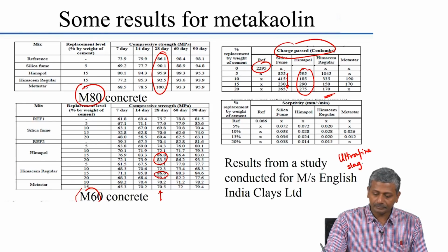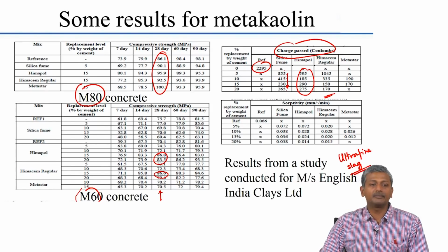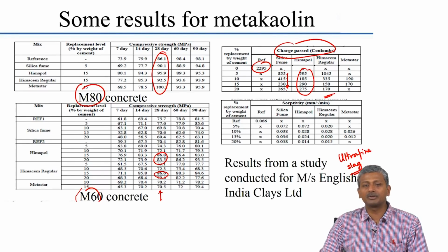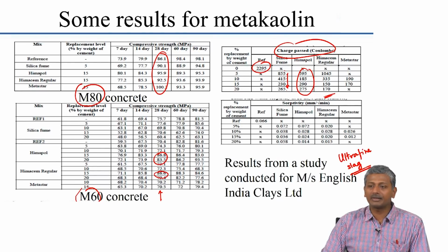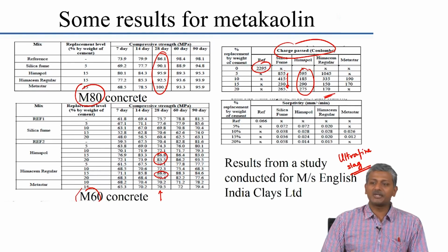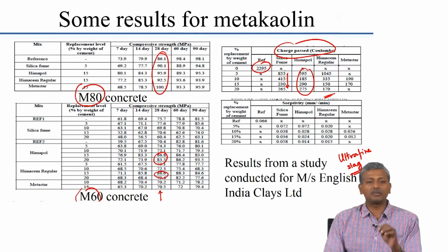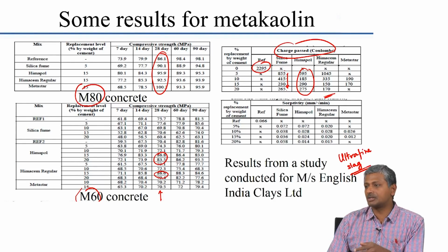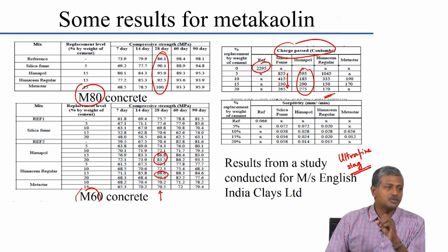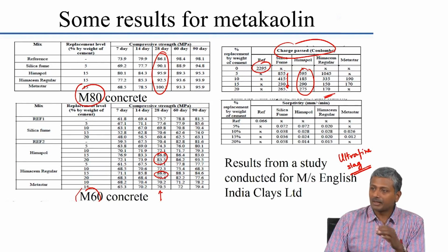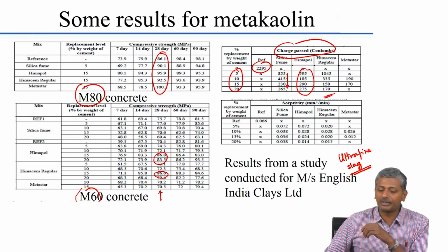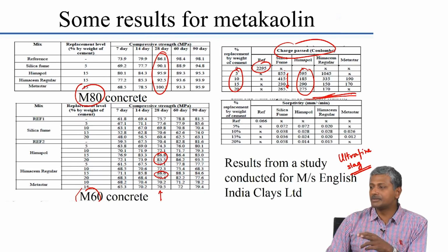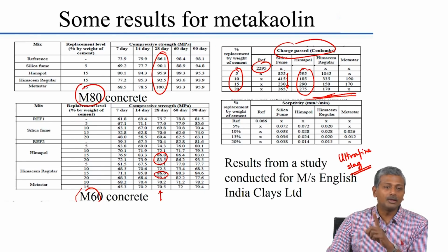Now, ultra fine slag can also help them enhance their strength potential quite well. For example, concretes of grades M90 and M100 can be produced with ultra fine slag. Interestingly, it has been seen that the reduction in workability that you typically see with silica fume and metakaolin will not be the same with ultrafine slag. You do not see the same reduction in workability, you see a slightly better performance when ultrafine slag is used. However, at the same levels of replacement, let us say 5 to 20% replacement, ultrafine slag can never get you the kind of numbers that are showing extremely low rapid chloride permeability.